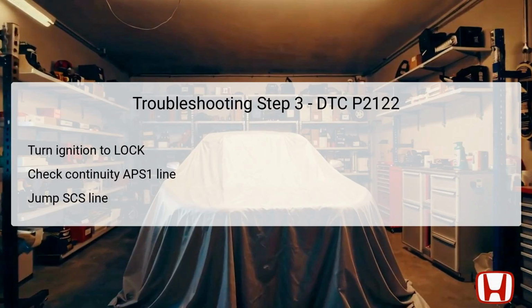Step 3 focuses on checking for any shorted wires in the APS1 line. After turning the ignition to the lock position, jump the SCS line using the HDS to prepare for the continuity check. Next, disconnect ECM connector A, 49P. With the APP sensor connector still disconnected, you will now check the continuity between test points 1, APP sensor 6P number 4, YL wire, and 2, body ground. This test should be conducted with the ignition in the lock position to ensure safe testing.